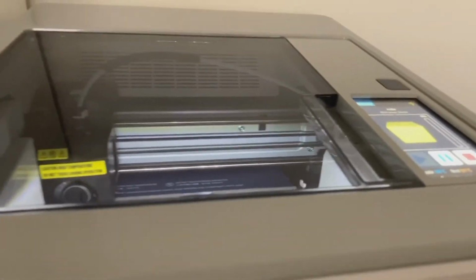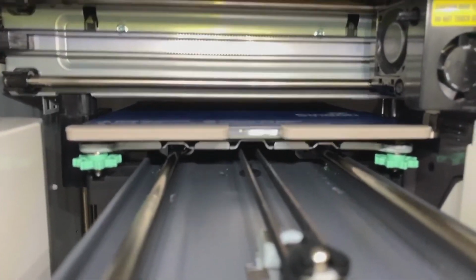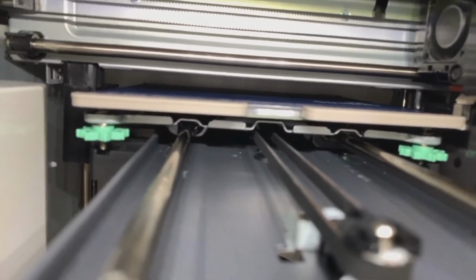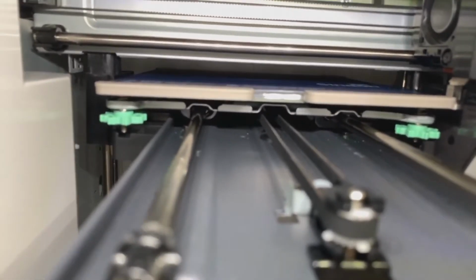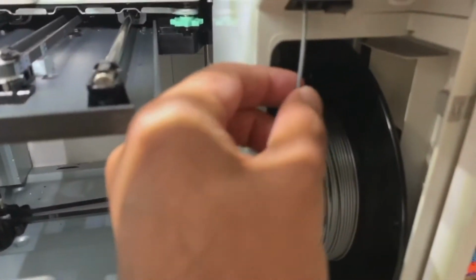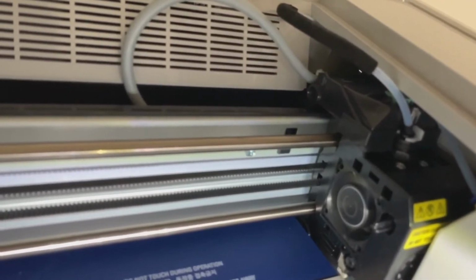But let's have a look at some of the actual pieces in here, right? So we've got the print head itself here, and what that does is move over the bed, and it's going to put down a layer of PLA, and it's just going to keep on constructing those layers piece by piece by piece. And that print head is fed by the print spool. So this is where you can see I've got a spool of material here, which is this plastic PLA. The PLA gets fed into the machine. It gets heated up on the head itself, just here, and then the head will melt the plastic and start putting the layers down.